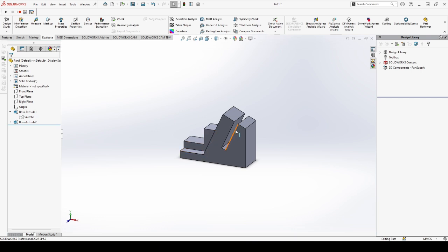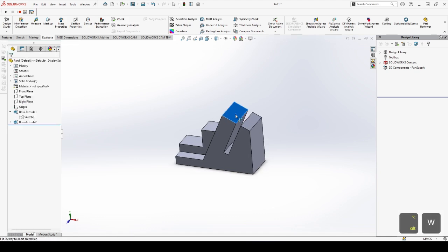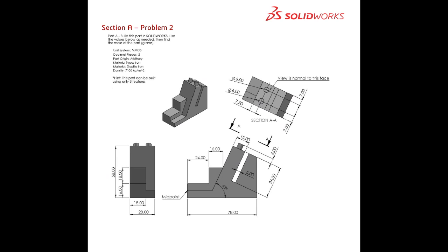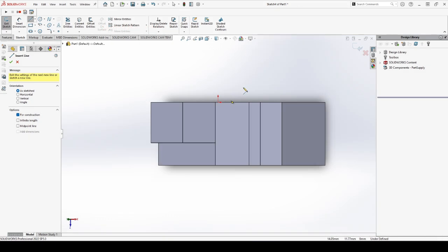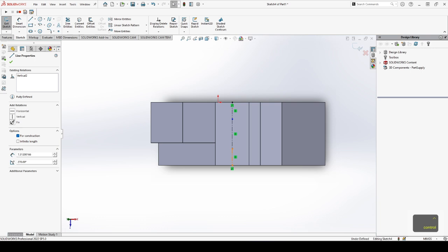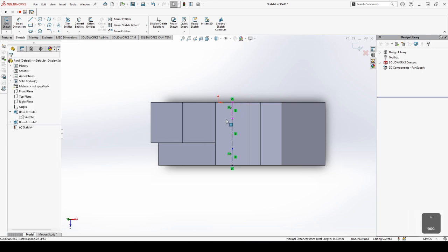Then lastly, we have the protrusions on our top face. So let's go ahead and do that now. Let's check our dimensions first and where it sits. So the width across our step or across our surface is 15, and the center of our circles lie along the center line 7.5, and they are both equidistant on both sides, 7 and 7, with a diameter of 6 each. So let's go ahead and do that now. We have 7 mils there, another 7 mils to the midpoint on that side. So let's equate these two. So we only have one dimension to modify if there is a change.